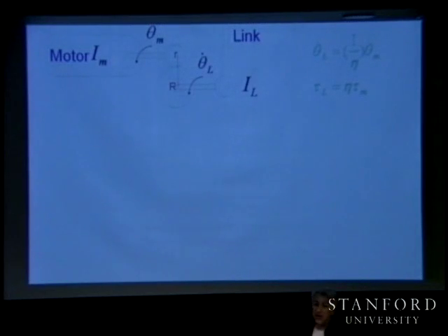And this something is... Twice the inertia of the motor. So you mean in general this is n times the inertia of the motor? Yeah, so it is n times the inertia of the motor, which is similar to the torque increase. The torque at the link is n times the torque at the motor. You're saying the inertia is in the same proportion, n times the inertia of the motor.